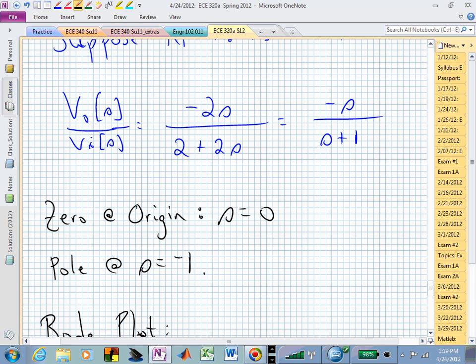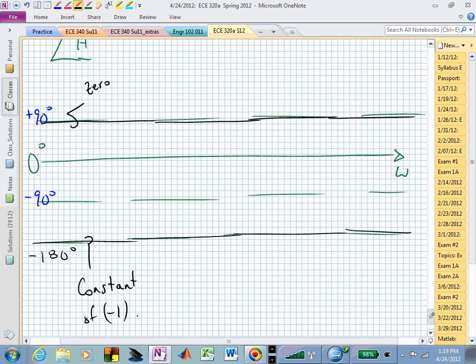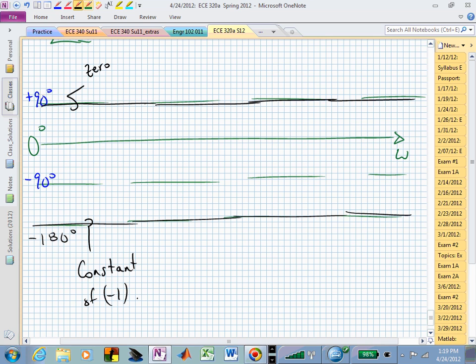And where do we center that 2-decade transition? Right at the break frequency. So we need to turn it on a decade before, turn it off a decade beyond. And a decade before, now we have to be a little bit more particular on this. Let's say that now we are 10 to the 0, 10 to the -1, and 10 to the 1.